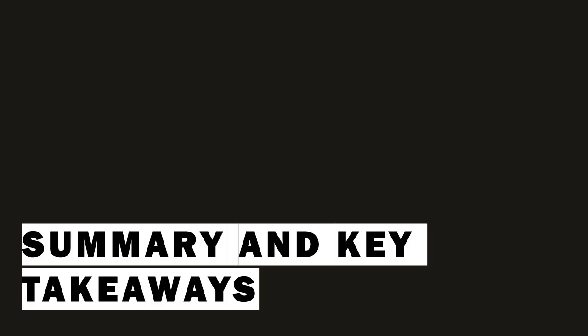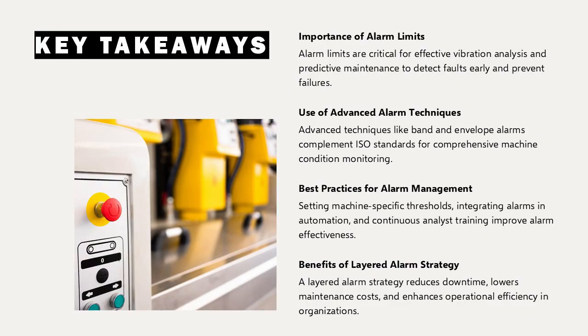Let's summarize the key takeaways. Alarm limits are essential for effective vibration analysis and predictive maintenance. ISO standards provide a foundational framework, but their limitations necessitate the use of advanced techniques like band and envelope alarms. Combining these approaches ensures comprehensive monitoring, early fault detection, and improved machine reliability.